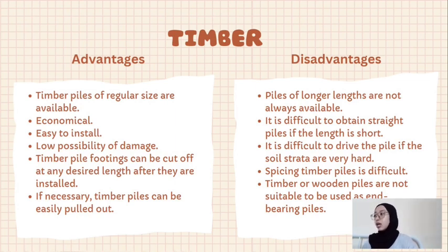Meanwhile, the disadvantages of timber piles are that piles of longer length are not always available. It is difficult to obtain straight piles if the length is short. It is difficult to drive the piles into hard soil strata. Splicing timber piles is difficult, and the last one is that timber or wooden piles are not suitable to be used as end-bearing piles.